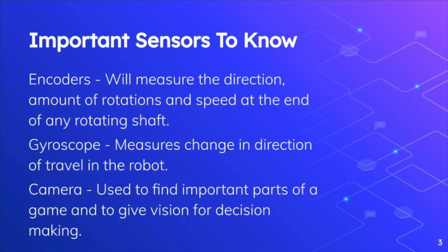And then a camera, which is very useful in FTC. Using various programs like OpenCV and visual processing libraries, you're able to determine maybe how far you are from a certain picture on the field, as there are many of those, especially all around the field and on the sides of the field. And I know this year it's on the brackets and whatnot. And so this is really helpful for overall determining how far you may be away from a certain coordinate.